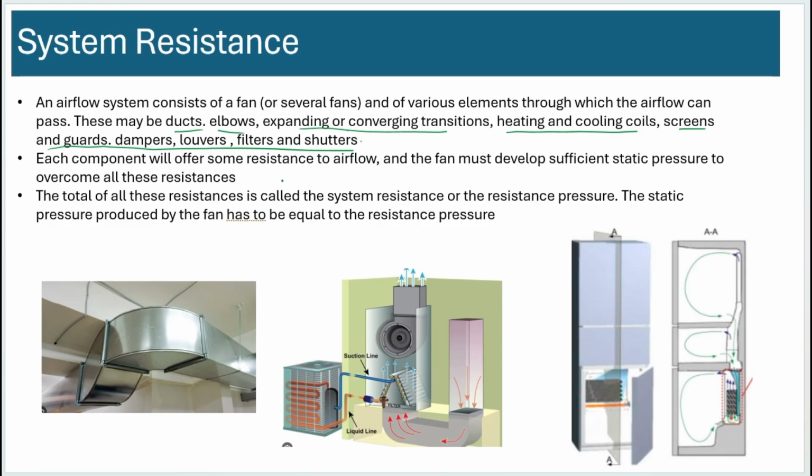Each component will have its own airflow resistance, and the fan must develop enough flow rate such that it can satisfy its primary function. And the primary function may be to cool a fridge, or cool a room, or cool a particular device. In those scenarios, it does need to provide the minimum required Q, overcoming all the pressure drops, right?